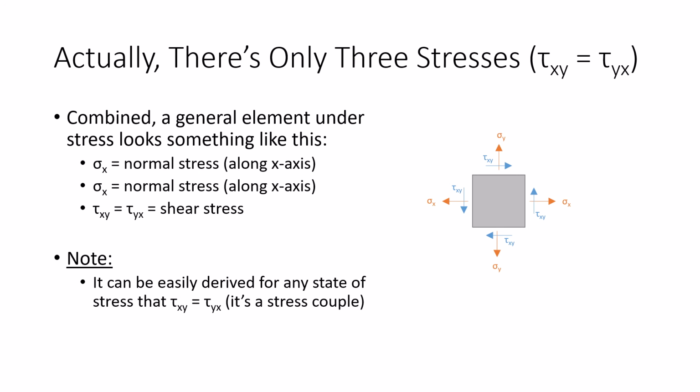And past that, all the arrow tips have to touch one another. So, for example, if I give you tau xy is 20, here's how you would represent it. The arrow on the right goes up, and then the arrow tips touch one another, right? So negative 20 would just be in the opposite direction. Don't worry, we'll have an example on that.